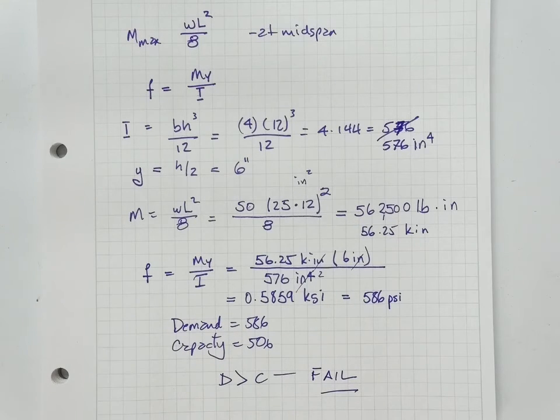And I looked at some catastrophes on Monday in a place I can't tell you about yet, where people forgot to put in the embedments, the weld plates and connectors. So a $10 problem becomes a $10,000 fix. I forgot to, or I put them in the wrong place. You want to know why can't you just go in and drill new holes? Because you cut the bars. And some of the bars, you can cut them. And some of the bars, you must never cut them. And you need to know the difference so that you don't propose something dumb.